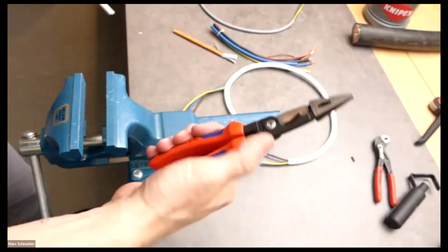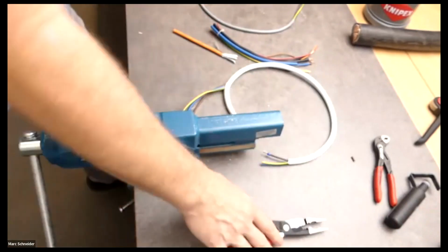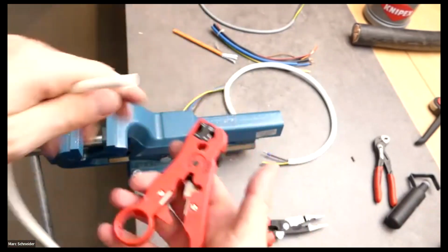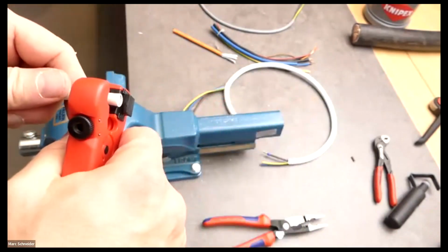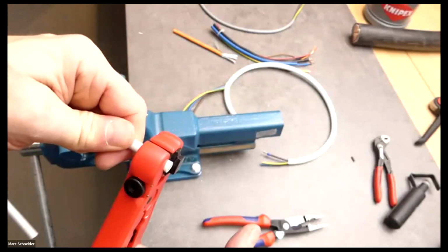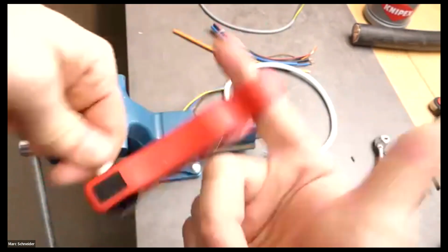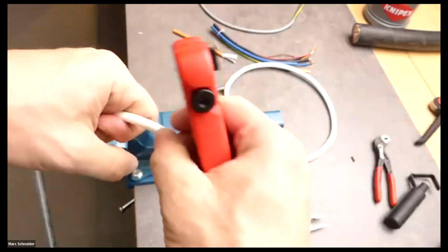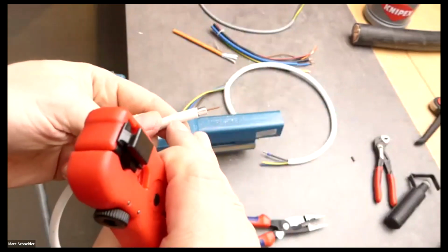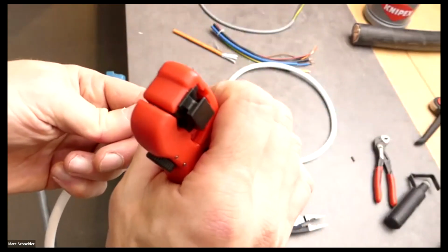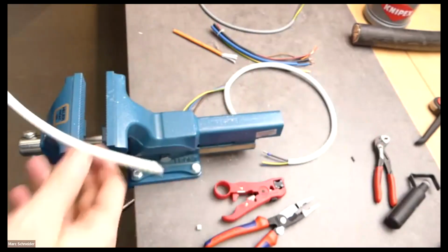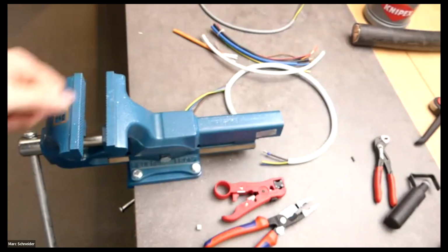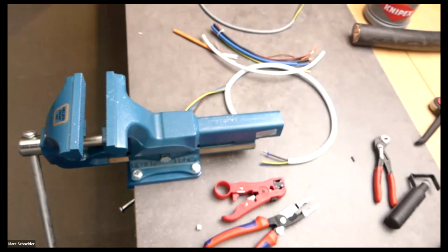We have also, if you are using only this type of coaxial cable, a special tool only for coaxial cable. You can use this one here. It goes from smaller diameters up to 11mm outside diameter. Put it here, turn with the finger the wheel, and that's all. Completely in one operation, you strip the cable in the right length. So you can also use this type of tool only for the coaxial cable. Yes, and that was it in principle, I think.